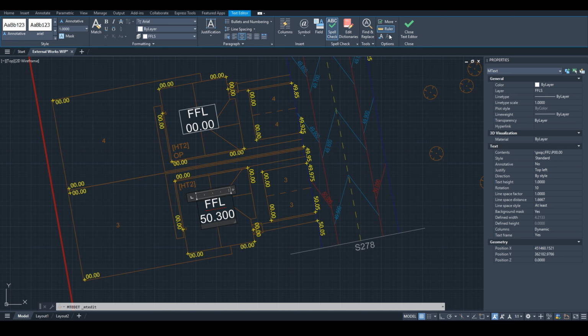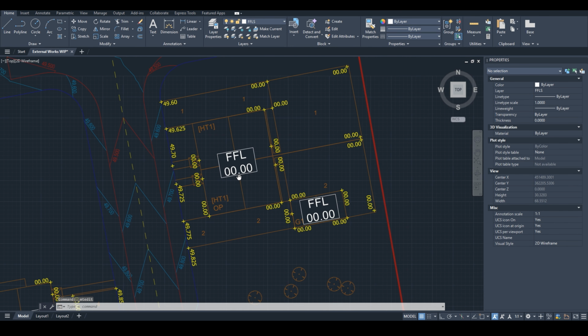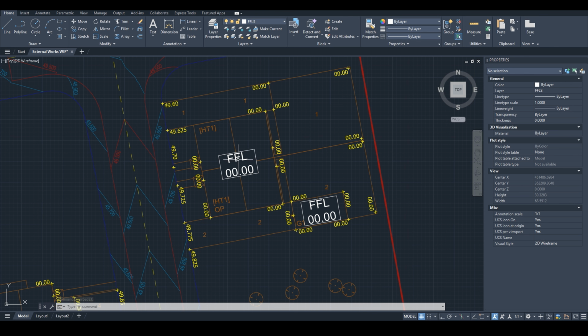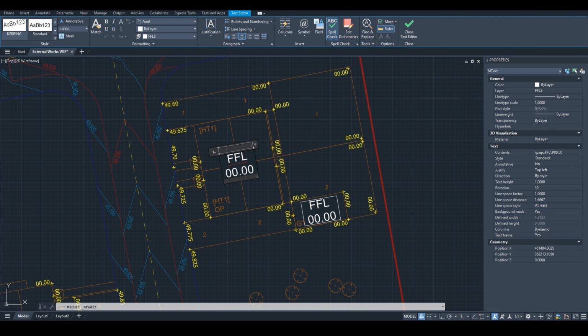Typically, you want the floor level to be at least 150 millimeters above the back of footway level. It's generally good practice to have adjacent plots coursing with each other. Try to only lift or drop adjacent plots in increments of 75 millimeters relative to the neighboring plots. This avoids potential difficulties with brickwork during construction. Garages should typically be 150 millimeters below the lowest adjacent plot.